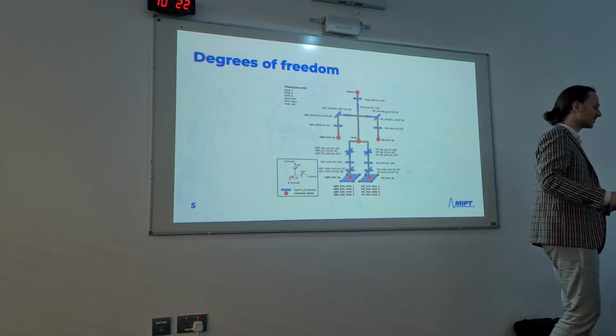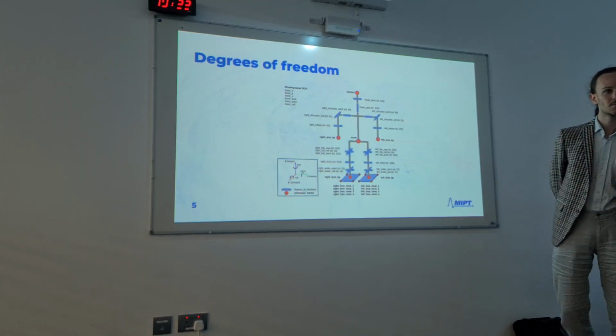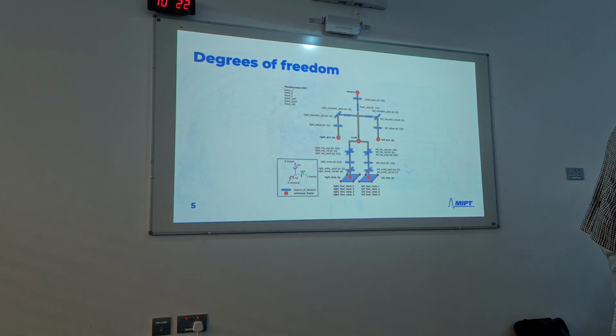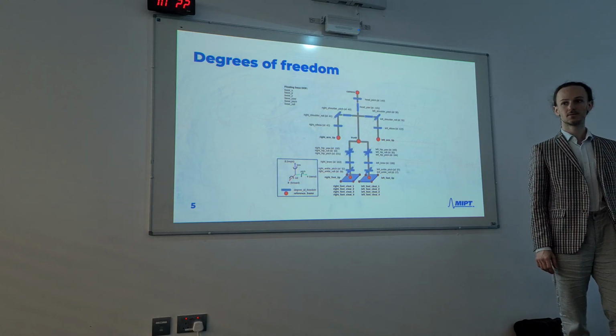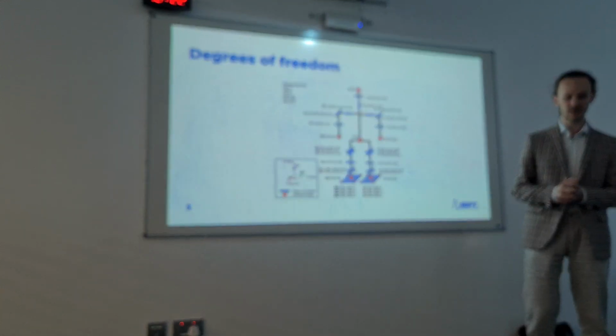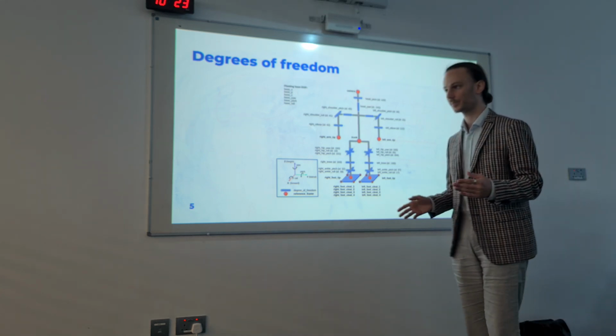How many wheels are in the robotic vacuum cleaner? Imagine 4. Why? So that's really neat or not? Two. Yes, indeed. So there are 2 wheels in the robotic vacuum cleaner, and it's enough for it as a differential drive to rotate and to move linearly.